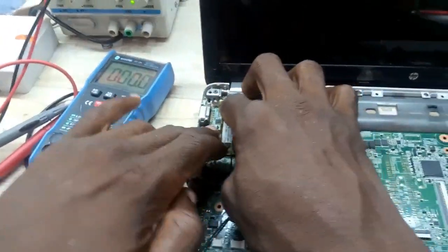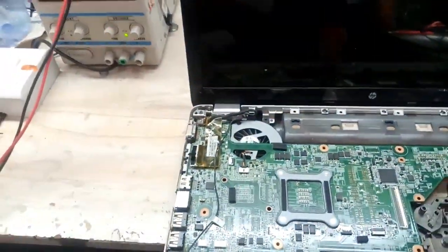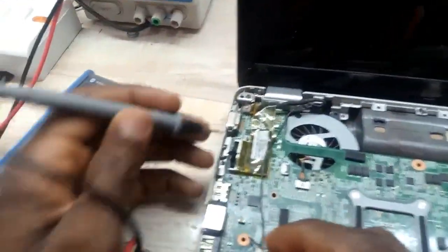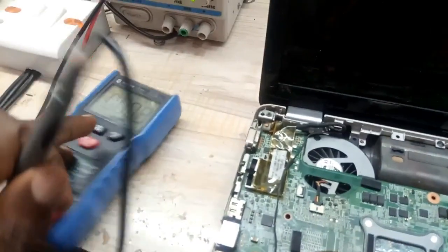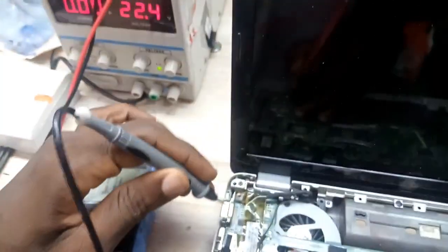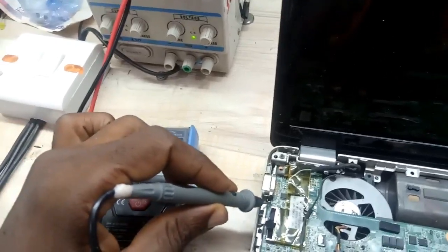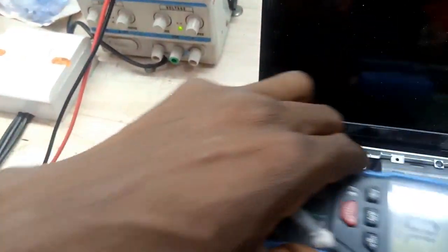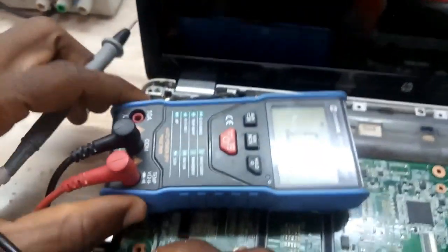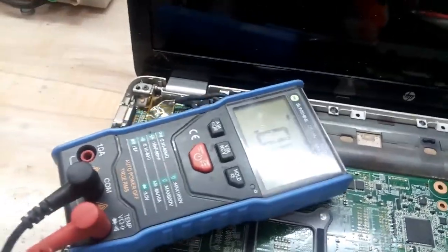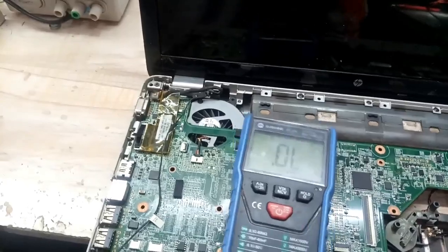The connector is in. Before jumping anything, let's see if that part is shorted or something, because the capacitors are not looking fine. So multimeter at diode range, and let's check what we have at the impedance. Let me place my multimeter here so I can see it clearly. What do we have? Okay, we are good.